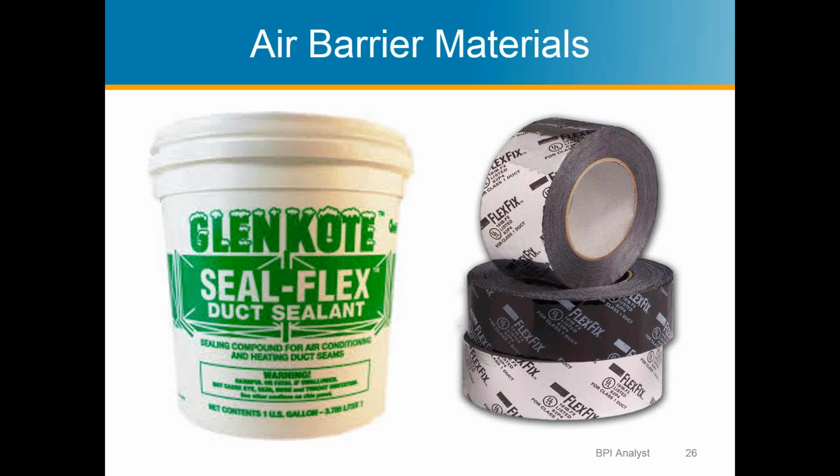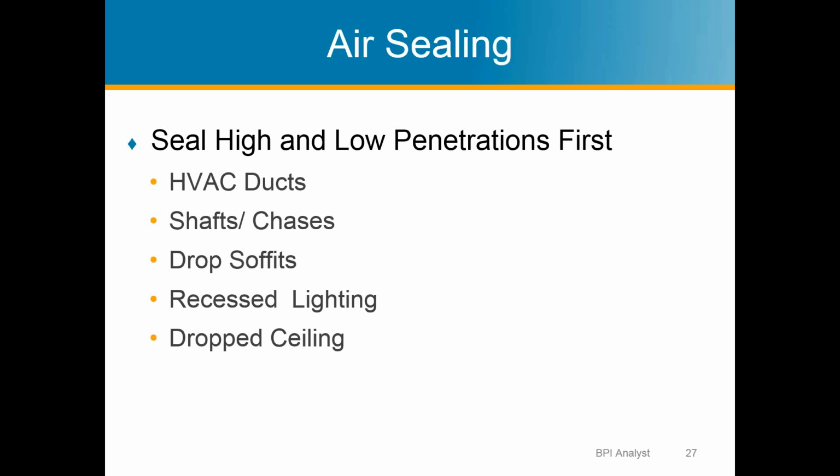And these are a couple of ways just to seal them. I've also used a lot of duct sealant to seal top plates in the attic and stuff, just because you can paint it on pretty quick and it works well if you're doing it by hand and not spraying.